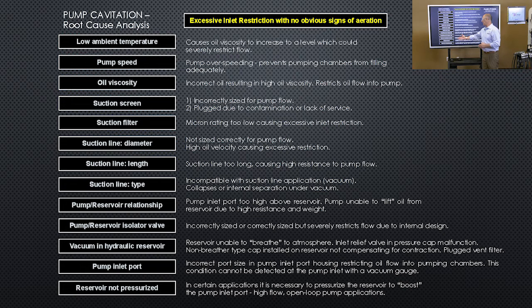Next, we have a vacuum in the hydraulic reservoir. That could be because of a breather that is plugged on a reservoir, because a pressurized reservoir filler cap has malfunctioned, or because the pump inlet port diameter is incorrect. And of course, the reservoir may not be pressurized, because some manufacturers require the reservoir to be pressurized. If it's not pressurized, it's going to cause problems at the inlet of the pump.